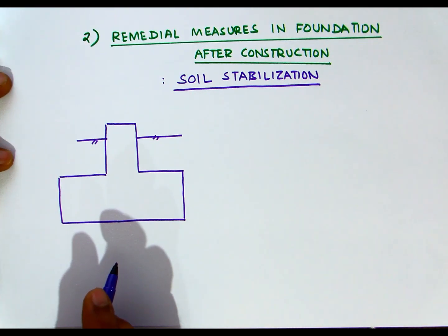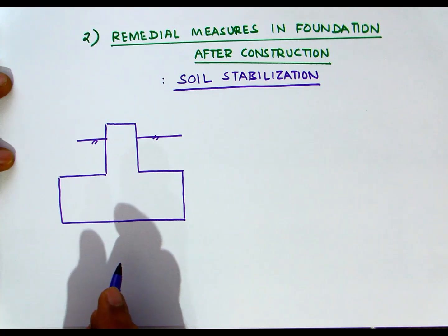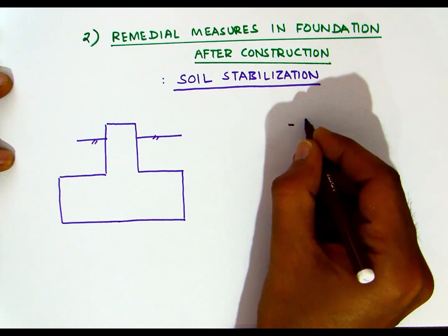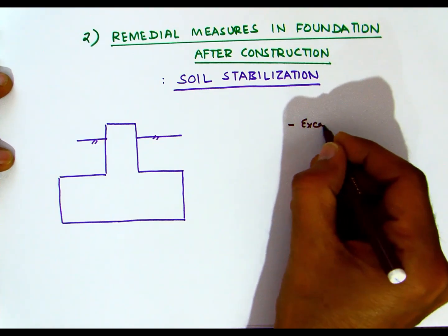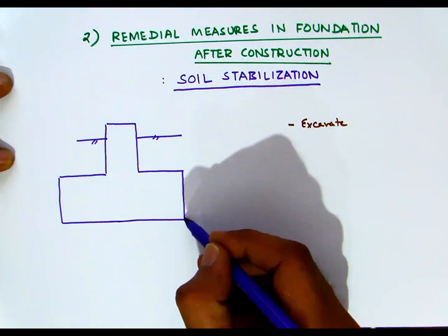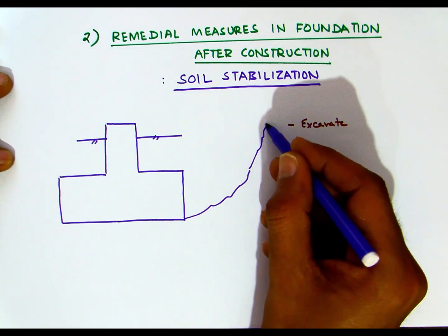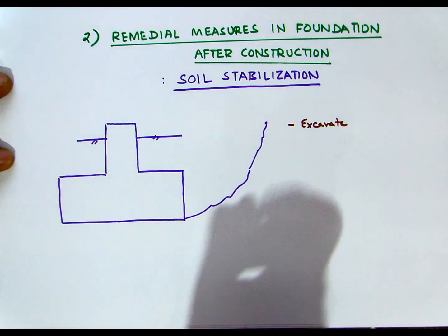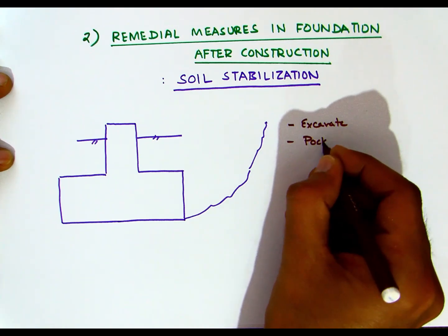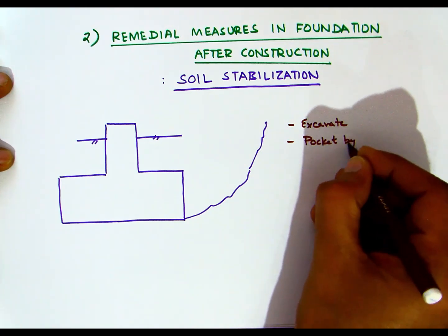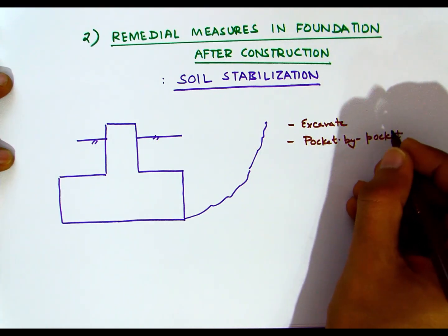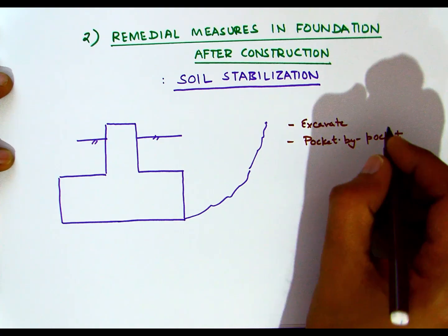What this step involves is excavation of the soil all around and reinforcing it in various pockets. So we need to do excavation all around the foundation. And then we make pockets one by one all around the foundation.